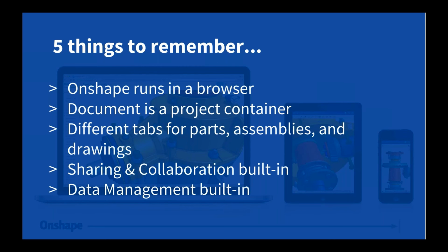One of the more common questions we get even today is, how do I download and install Onshape? And the answer is you don't. You log in through any WebGL supporting browser. This is Chrome, Opera, Firefox, Safari. You want to avoid Internet Explorer and Edge. So again, Chrome, Opera, Firefox, Safari all work great, but keep in mind you do not download and install Onshape like you would other CAD applications. It runs entirely in the browser. So that's probably the most important thing I would stress if you're just getting started with Onshape. You won't find a download link. You just log in through the browser.